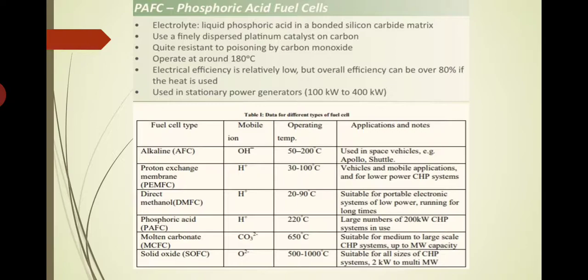Okay, so all these fuel cells are basically different from others based on which electrolyte is being used, as well as which fuel is being used. Mostly the fuel used will have some hydrogen content in most of the cases, and of course oxidizing agent, on the cathode side we will be supplying oxygen. Okay, so the lower figure shows this one. This table shows the comparison between all these types, or we can say in a nutshell what are the mobile ions. We will have an idea.